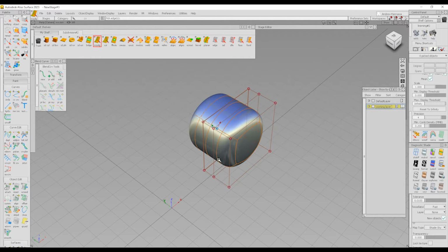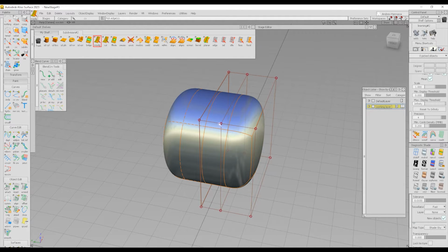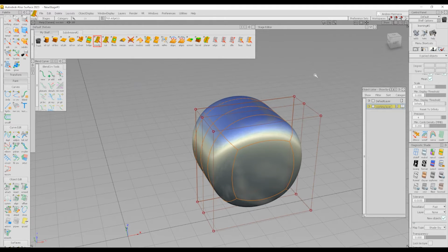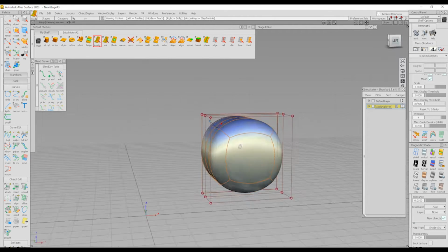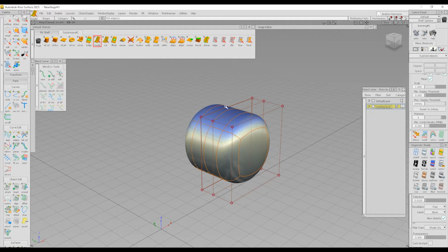What we have to do is keep this edge loop, wherever this CV is, or this set of CVs in this edge loop, in an identical position in XZ in this view, so that we can maintain symmetry, or curvature across the center line.